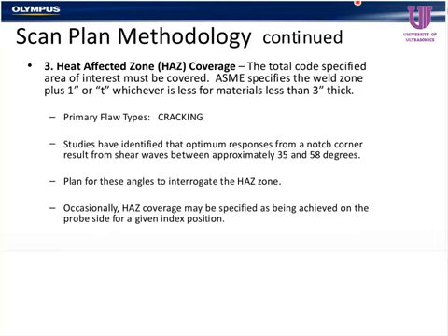We choose those particular angles because of their ability to properly place a corner trap type signal in the proper location. Meaning if a crack ends up being connected to either the ID or the OD surface, those particular angles are better for determining that it is surface connected.